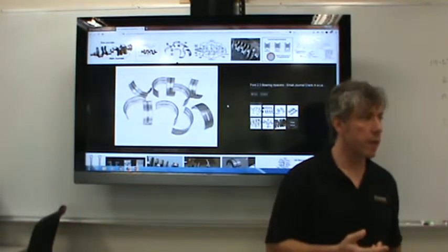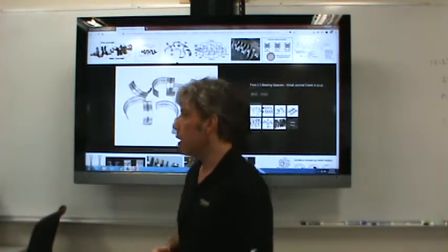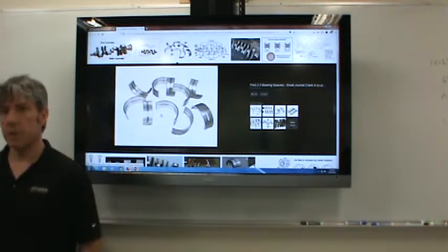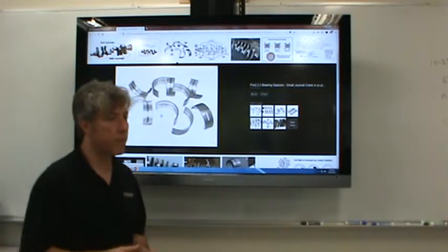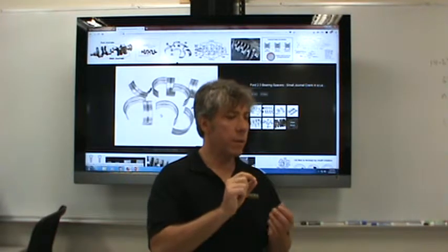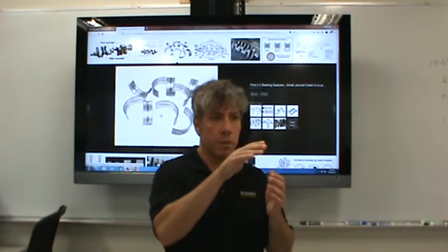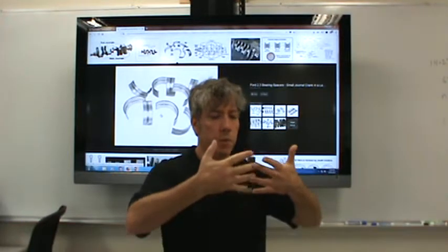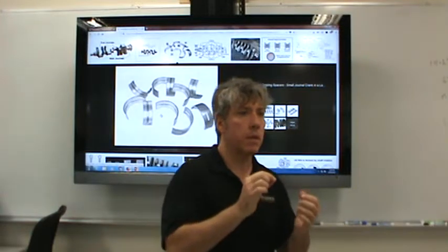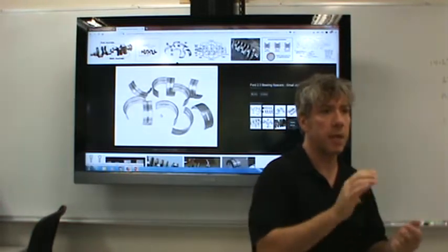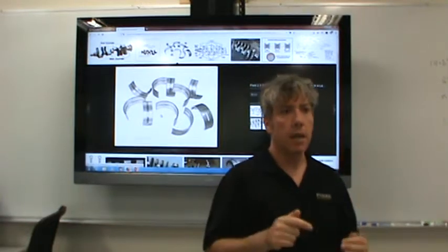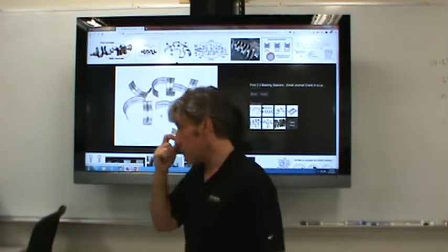We'll learn more about journal bearings as we go. There's a whole chapter on plain bearings. But anyway, the reason the surface finish has to be so fine, there's a couple of reasons. One of the main reasons is the tolerance between the journal and bearing is so small that if the surface was not very smooth, the surfaces would impact each other. There would be very high wear, think about it like sandpaper rubbing. Sandpaper removes material because it has a bunch of ridges and valleys in it, right? Well, that's what we don't want in this crankshaft: ridges and valleys.